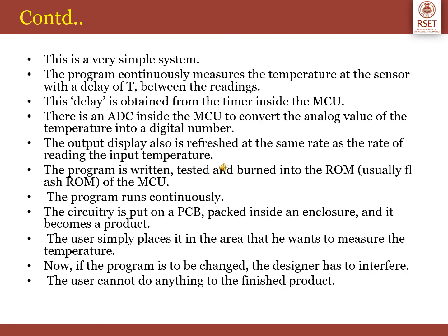So this temperature monitor system is a very simple system. The program continuously measures the temperature at the sensor with a delay of T between the readings. This delay is obtained from the timer inside the MCU. There is an ADC inside the MCU to convert the analog value to digital. The output display is also refreshed at the same rate as the rate of reading the input temperature.